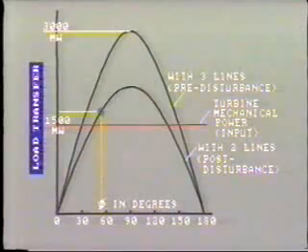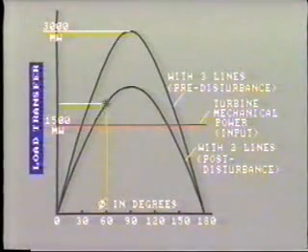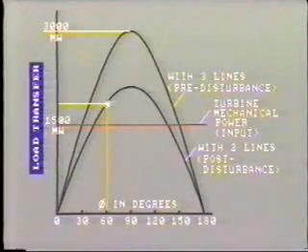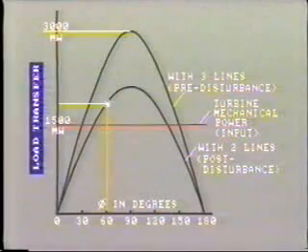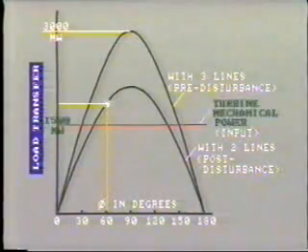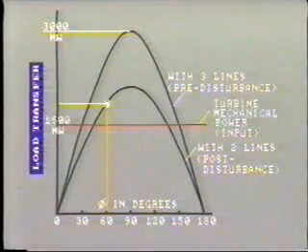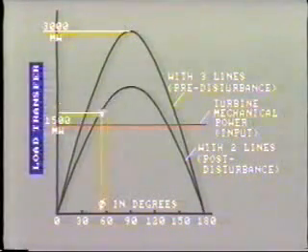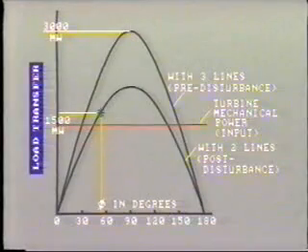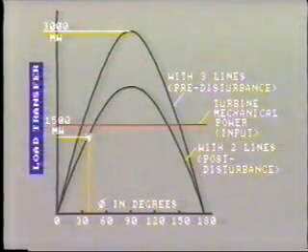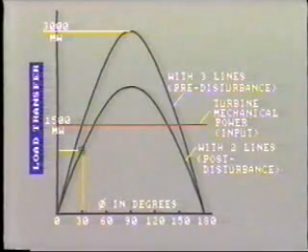In fact, the rotor overshoots and continues advancing in phase, so further increasing the amount of power being transferred across the line. However, now we have the situation where the generator output is greater than the mechanical input. So the rotor starts to decelerate and fall back to the equilibrium point. After a few oscillations, the rotor will settle again at equilibrium.